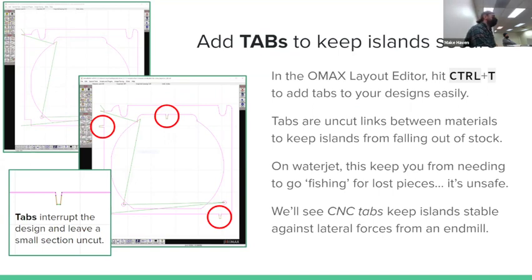You can stop the cut and switch the side of where your vises and grips are, so that it holds on to the part that's going to fall off. And then cut next to it, so that now it doesn't fall. It would have hit your grip, but then you switch it to the other side and it cuts through there, and then you hold up. And don't move anything else in the meantime. Sort of like rock climbing, you need to have a few points of contact. Always have two places.